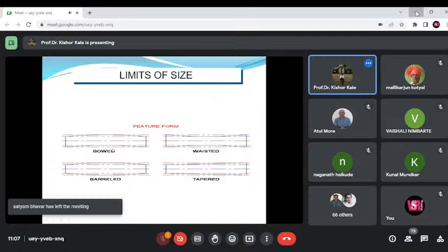The last basic thing we will look at is degrees of freedom, because this is very important while specifying in the CMM, the coordinate measuring machine, and the scanners, which are the tools of modern inspection. They work on 6 degrees of freedom, or tolerance itself works on 6 degrees of freedom. Sometimes in some literature, this is also called 12 degrees of freedom. It's very simple. We have 3 linear and 3 rotational degrees of freedom.